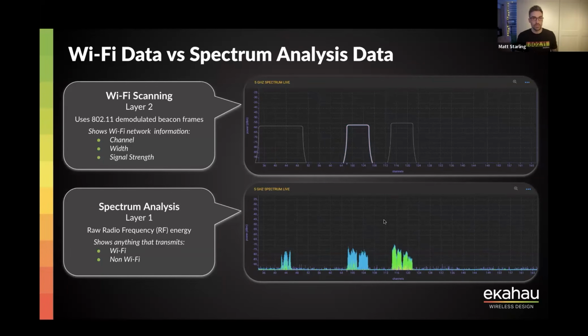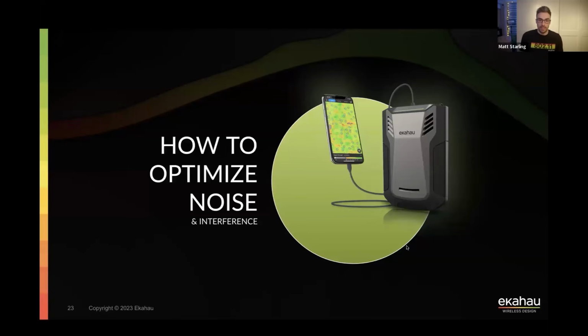So one of the things that I like to do is when I've got my Sidekick 2 connected to my Ekahau AI Pro, and I want to visualize what's happening over the air, I like to connect my phone to my access point and run a speed test, because that forces a big push on the upload and then the download. So the traffic on the channel gets very busy, and you can see that information and energy transmitted across the channel. Also, if we had any interferers in my environment, let's say I had a video camera or a passive infrared device that was operating at 5 gigahertz, this is where we would see that signature and that detail in this view right here.